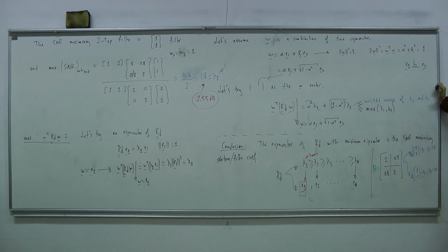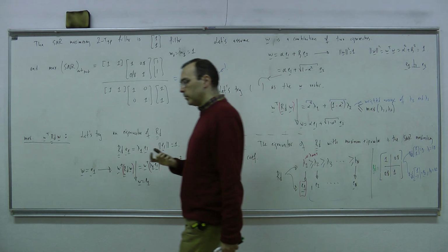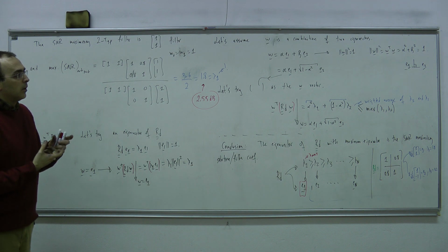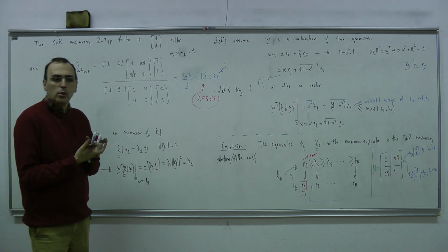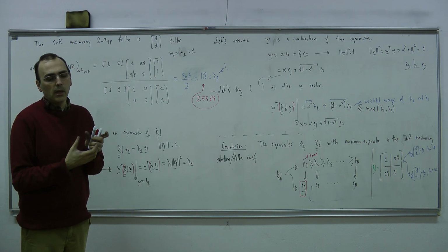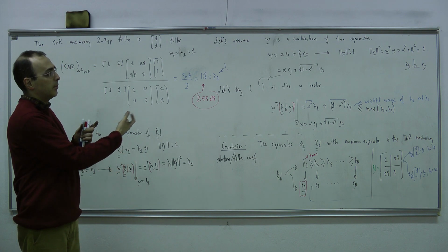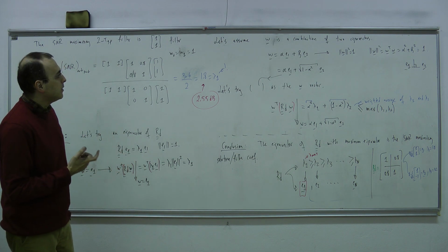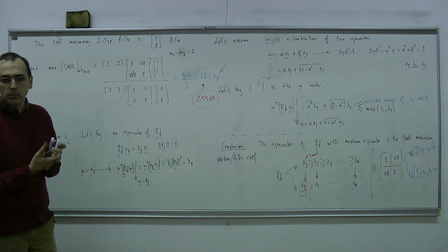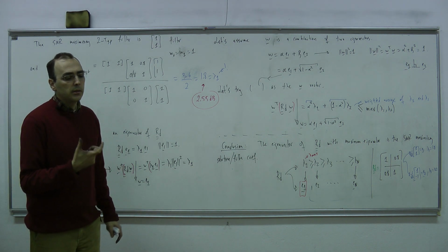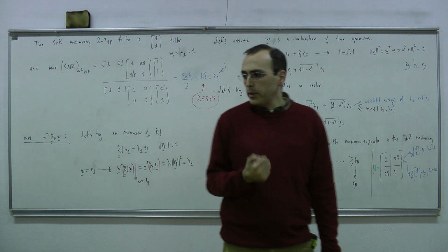So what we have seen today is FIR Wiener filtering. The Wiener filter reduces the impact of noise on the observations. So it's like a noise removal filter in this application. But the reduction of the noise, or the improvement in, let's say, signal quality, can be an important measure.